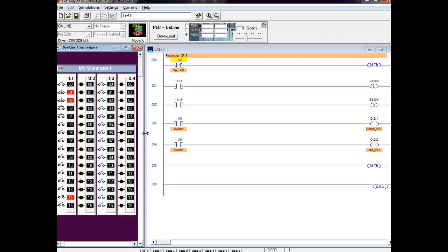Because these guys are radio control cranes, and if they lost what we call their reset, it dropped out all the relays that were controlled by the control system. So the problem is that if we lost your reset or somebody hit the e-stop button, we still don't want the magnet to do what? Drop the load. So we use a latch and unlatch relay, but we don't kill that output with an e-stop. Y'all understand that? So everything else you can kill with an e-stop. That's what I'm trying to show y'all here, what this would do. So if I didn't have it latched, it's okay, right?